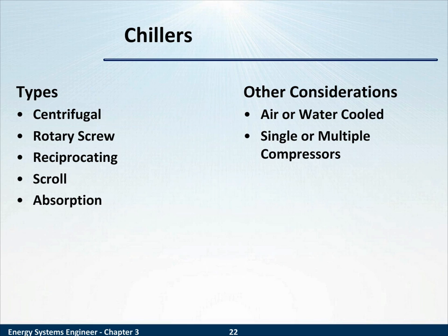Whereas reciprocating chillers are rumored to be going out of favor because of the comparable efficiency from cheaper solutions, the other three predominantly share the market based on capacity, based on this stratification. The first is in a small 10 to 100 ton application.